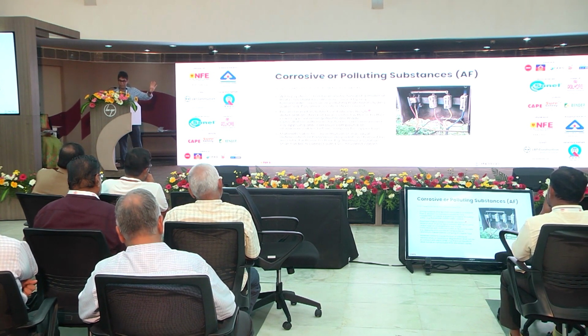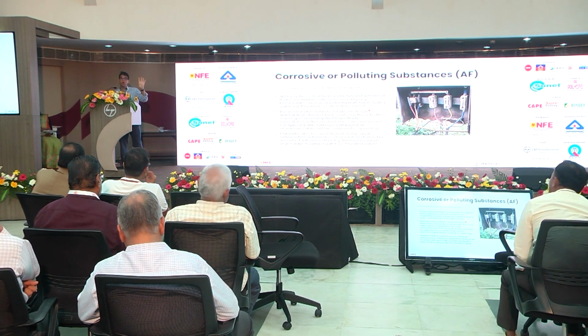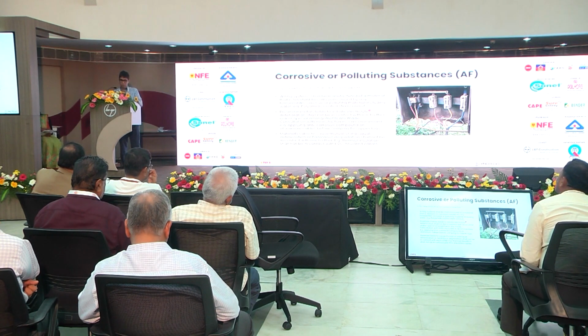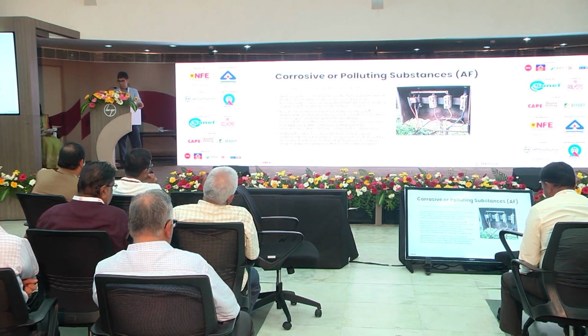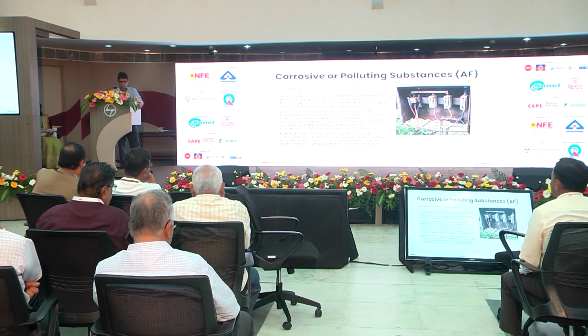I saw a bad case of this in Hyderabad once, where an entire bolt had rusted. And then that guy's impedance in his house was 20 ohms from line to neutral. So again, this is a simple thing. You just look at the manufacturers that make this anti-corrosive material. You follow the manufacturer's instructions for the termination of aluminum cables or the copper cable lugs for use with aluminum cables, and you're good to go.